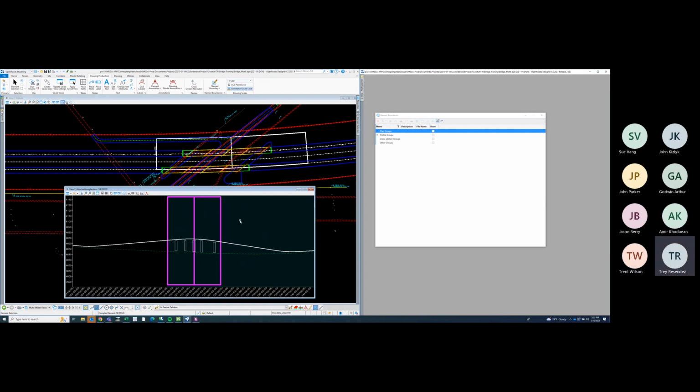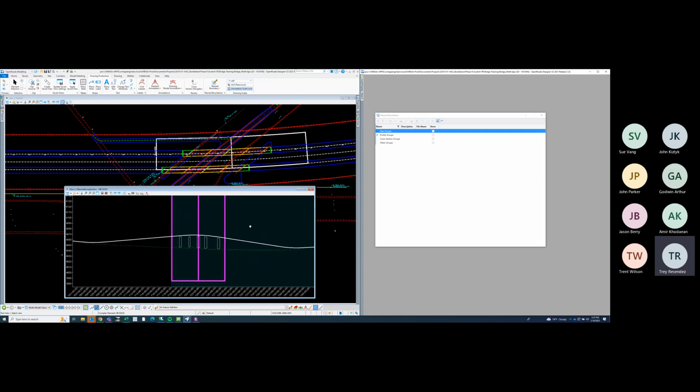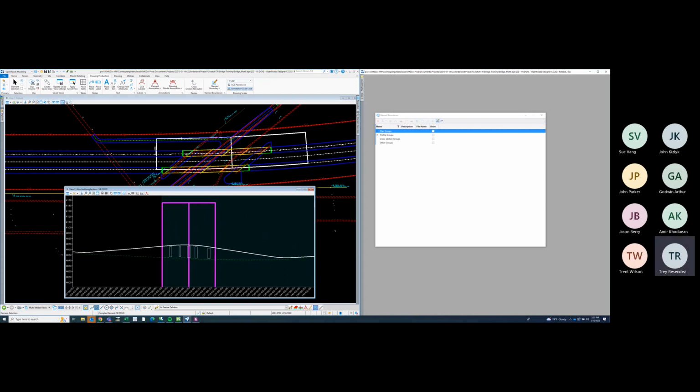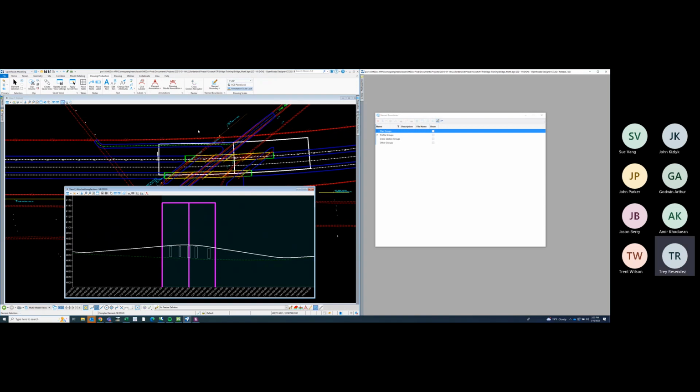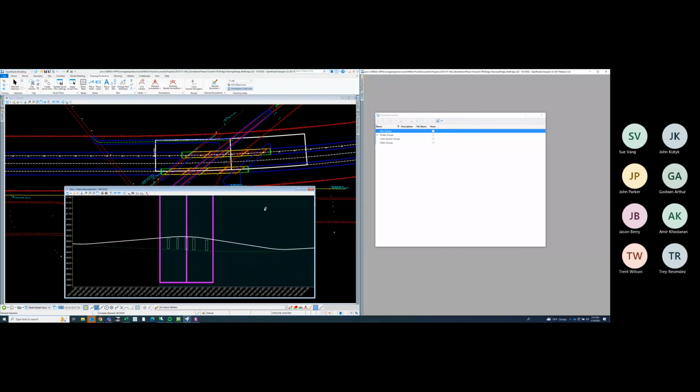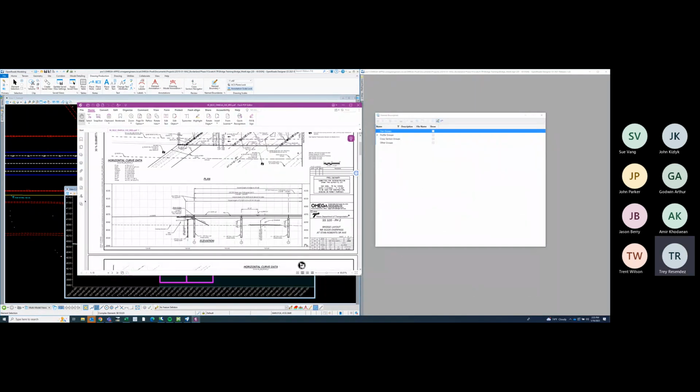Yeah. Gotcha. Yeah. So you're gonna want to change the vertical exaggeration, whatever you want it to be, and then you'll make sure that the length of the name boundary will make sure that it's a multiple of 1200. So as long as you have those two things, then it'll come out. Then it'll show up within the limits of the sheet, I guess.